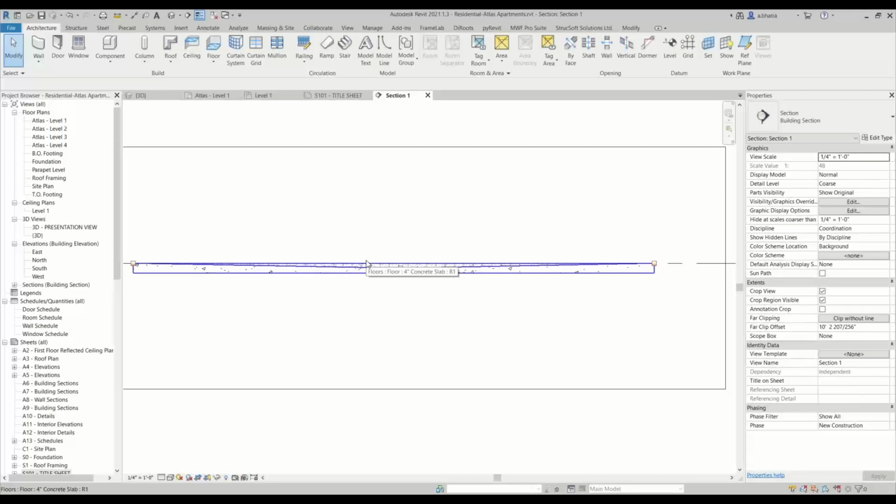It's totally understandable. When you have a situation like that, we always recommend to create your structural layer of your floor the way you need it to be created, and then have your tapering or your variable values to be another layer on top of your floor, or like another floor that gets placed on top, or another roof that gets placed on top, okay? And the reason for that is this is really bad for structural integrity.